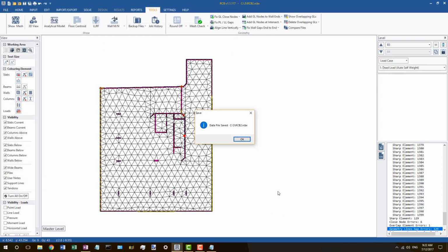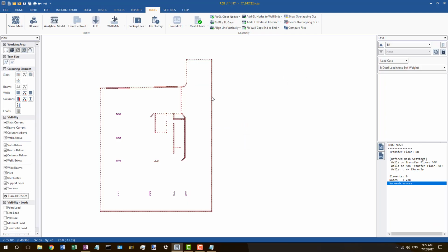And we'll start by cleaning up the floors, going from the bottom level up. So now I'm going to go ahead and tidy up this model, adjusting geometry lines, walls, columns, etc. to get it meshing without any errors. So basically I'll just be talking for the bottom few floors, and that's where I'll discuss all of the key principles, and then I'll continue on the upper floors, but without talking. So if you don't want to watch the rest of this long video, you don't necessarily have to after a certain point, after I discuss all the principles.